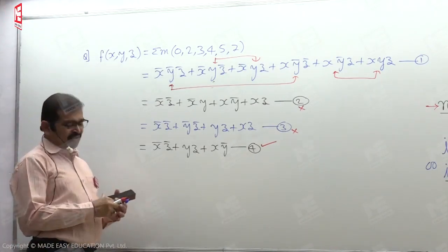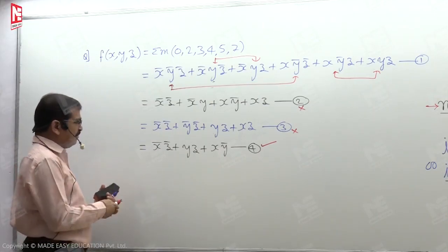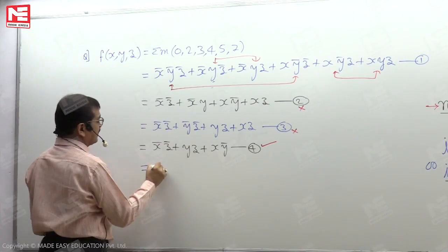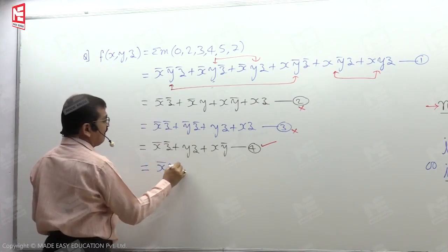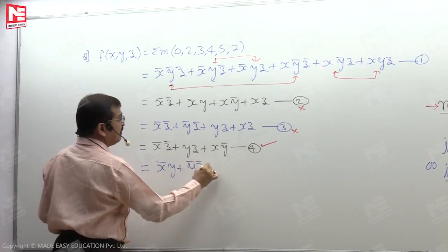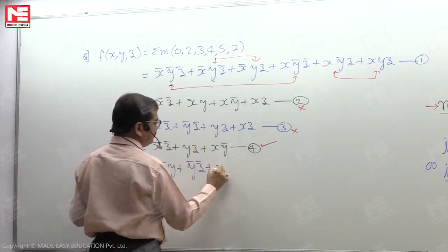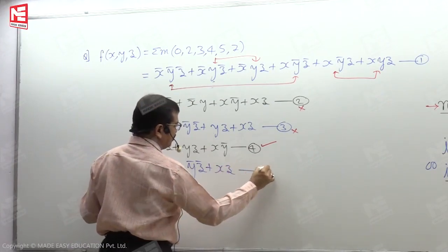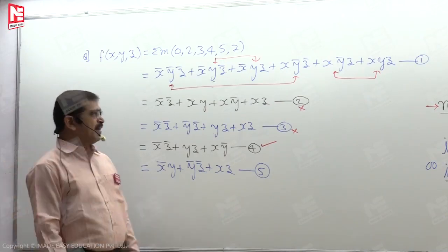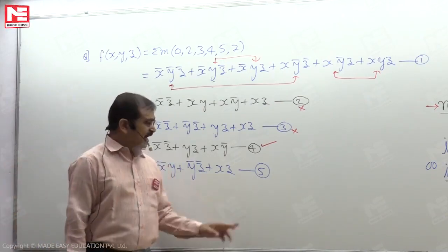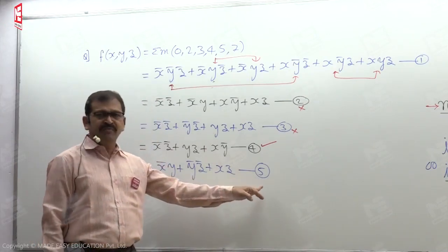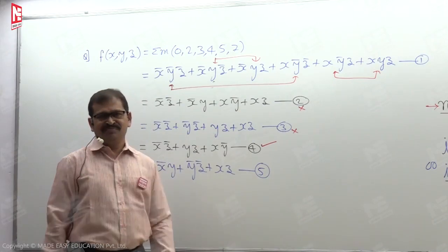So with this grouping covering every min-term, the expression is as follows. From the second and third terms, we get x complement y. From the first and fourth terms, it is y complement z complement. From the last two terms, it is xz. That is named equation 5. Equation 5 also has fewer terms compared to equation 1, so definitely it is one of the possible simplified expressions.